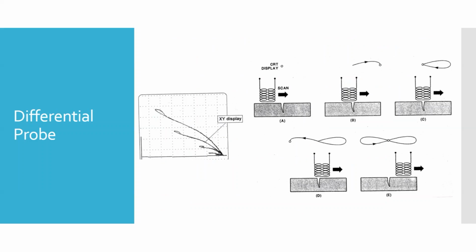Okay? But if you have a very small crack, especially one where the probe itself, the coils are larger, you'll often get this bow tie shape, where there's a big enough difference in size between the probe face and the flaw.